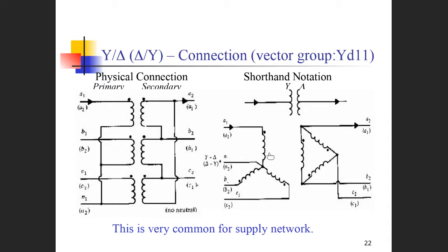On the star connection side, we used to connect computers, motors, and whatever, chillers and drills. So these loadings are not pure resistance, and they have inductance. As you know, when there is inductance and capacitance, they may change with time, change with the current, making the system nonlinear. This non-linearity on the loading side may induce harmonics.